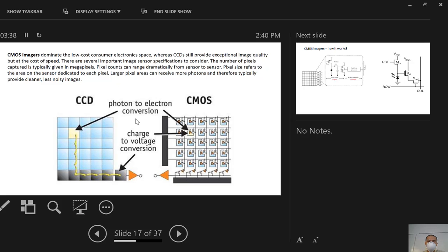There are still many people working on CMOS technology to improve the speed, the resolution, and the aspect ratio. The aspect ratio is the area of the photodiode divided by the area of the pixel, because only the photodiode is photosensitive, but the capacitors are not.